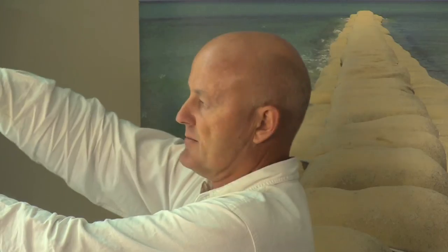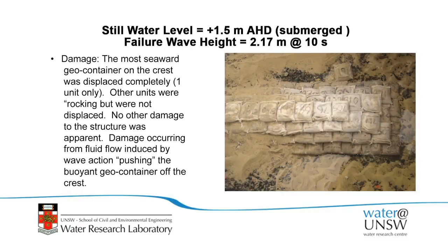So that was the only damage we had at the really high water levels, was the crest one started peeling off. If you've ever been up to the Maroochydore groins up here, not far north of here, you see similar damage mechanisms to what we've seen here. In some circumstances, these bags are taken out, but after the really big storms, it's the crest bags that get taken off.